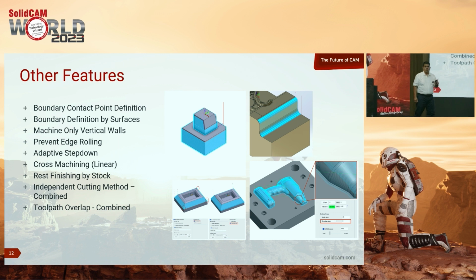A couple of things to note. There are conditions. If you're trying to open your old part in 2023 SP2, when the Unified engine will be available, and if your old part does not have any Turbo 3D HSM toolpaths, Turbo 3D HSM will not be seen in the tree. Okay, you'll only see the Unified toolpaths. You won't see Turbo 3D HSM.